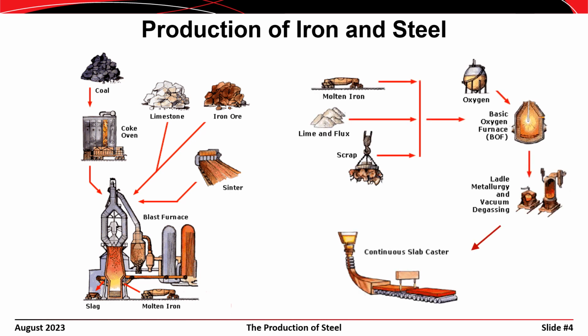That might be directly going into a basic oxygen furnace. That might be going into some ingot facilities or something like that. Basically, you combine the molten iron with lime and other fluxing agents, and maybe with some scrap metal as well, and you get from the iron step in the process to the steel step in the process. And then after you have all of the chemistry right in the heat or the batch of steel, then it goes into a continuous caster or into some type of a roughing and finishing operation.